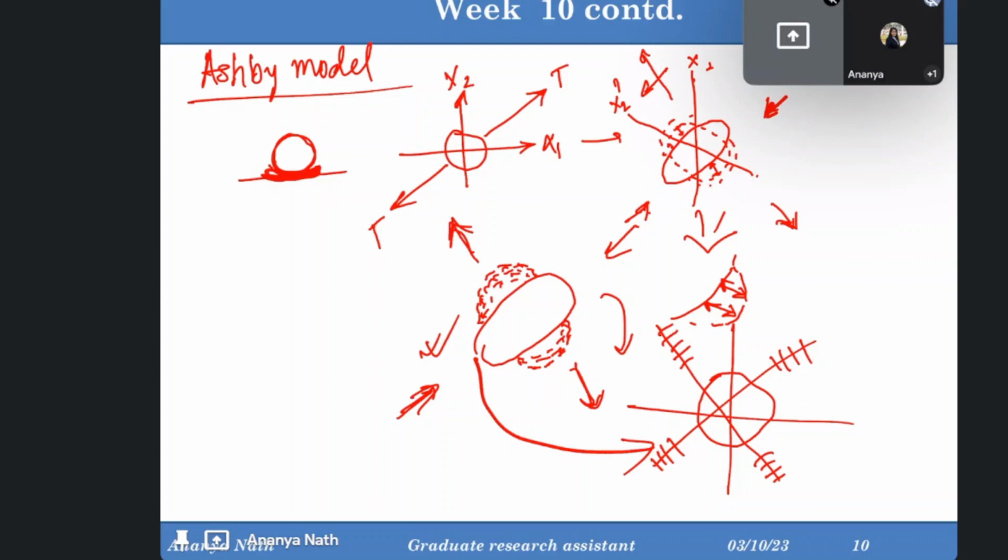Ma'am, it is never actually possible that you will spread the dislocations equally on every side. We can just spread the dislocations to some extent, but with an equal number of dislocations on all four sides, it's never possible, no? It's just a model. Ma'am, if the particle is spherical, that means all around the particle we have the dislocations, right? Yes, because there is an interface.